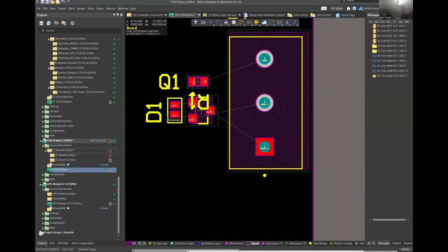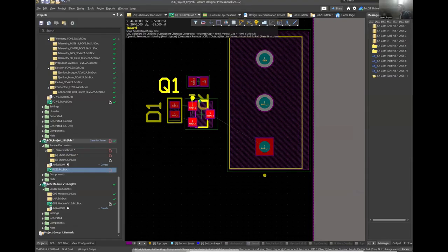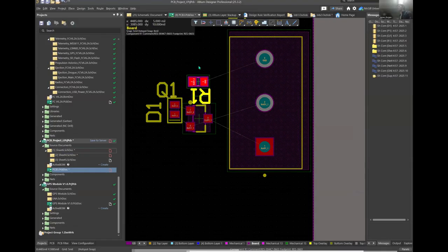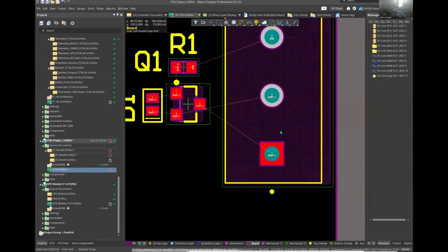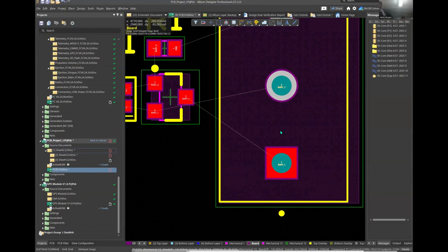How would you actually implement on an actual PCB board the crossing of the two connections? So let's say it wasn't possible for me to switch these on the connector, which I would just do by going in my schematic and actually flipping these two pins. So I would go, okay, net D1 is actually connected to pin 1 and net P1 is connected to pin 2. But if that weren't possible, I would just figure out a way to route this in a way that worked.